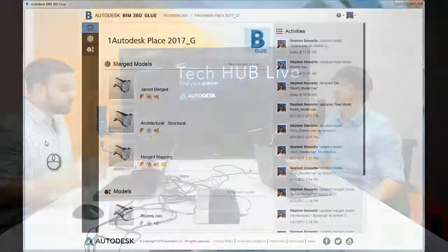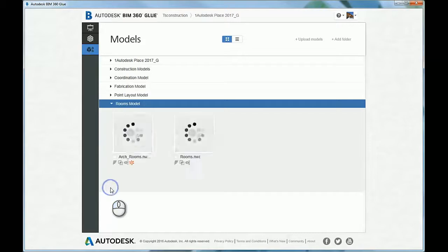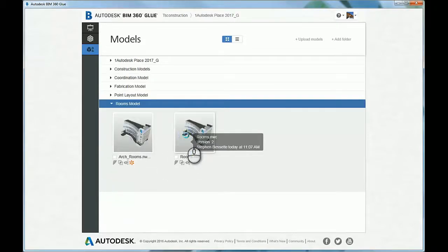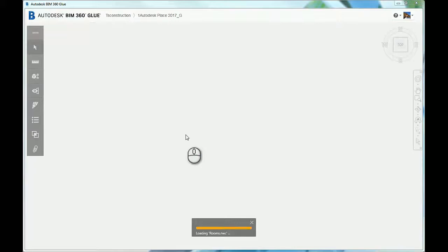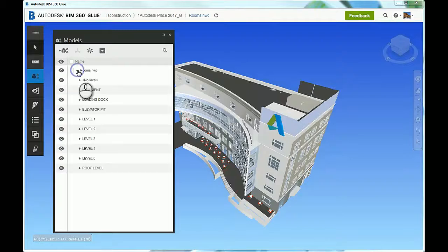Exactly, because rooms are not an actual physical object inside of Revit. So when you look at a 3D model and you select the entire model, rooms cannot be filtered out. What this does is convert that fake 3D bounding area into a true 3D area. So when we look at creating equipment sets and jumping into this model, you'll be able to see that it is actually selectable, and it includes all of the metadata that came from Revit. So if you have room finishes, anything customizable, whatever's in the properties dialog box inside of Revit will be inside of Glue. Definitely. And subsequently, eventually into Field.